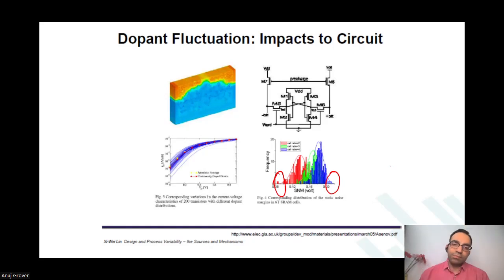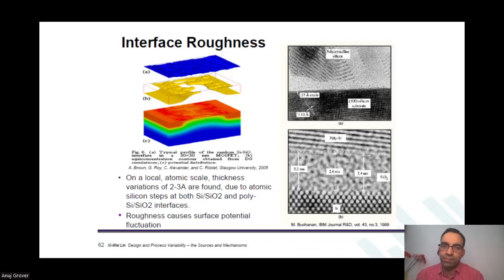So again, this is about the impact it has on the memory cell. This is actually the memory cell's SNM analysis only, where we say that for different SNM values, how is the distribution when cell ratio is moved from 2 to 3 to 4. And this has considered only the random dopant fluctuations as part of the variations as yet. Other random things are not put in the picture.